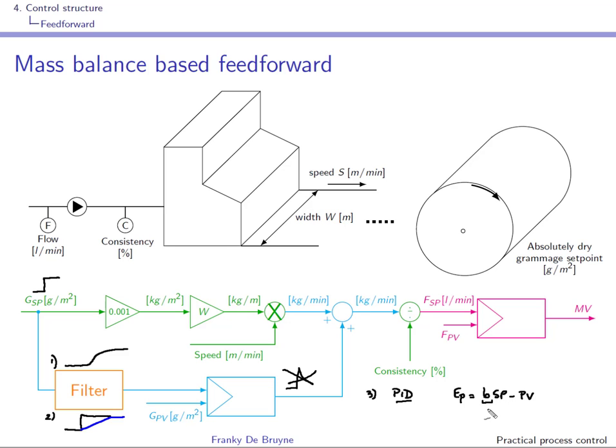And you put this b to 0. You see that the influence of the set point is taken out of the proportional error. Of course, the set point is still present in the integral action, but not in the proportional part, and this will also prevent this kick at the output. As I said, this will be viewed in the next section.